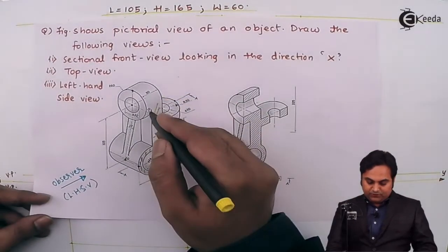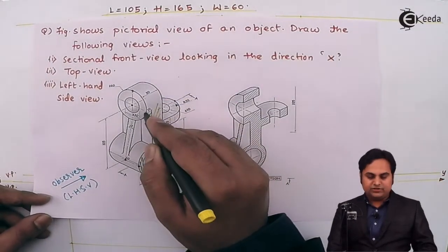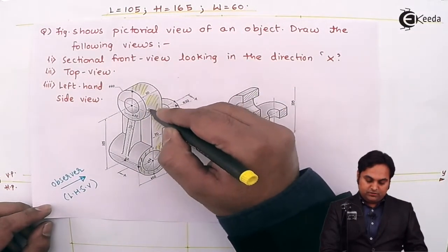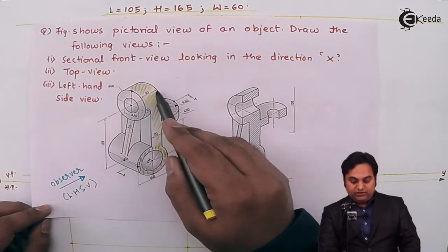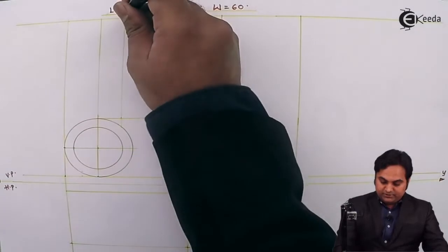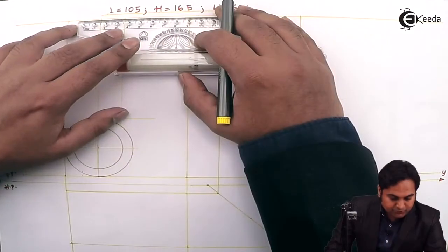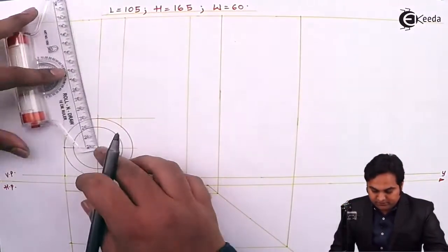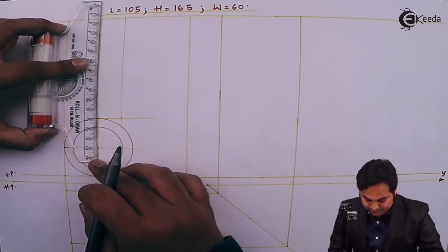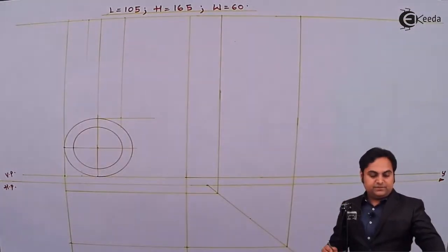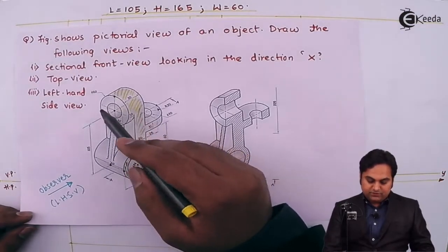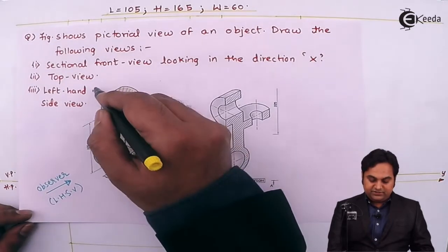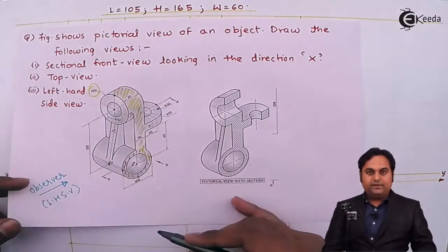After that, from this center, that is exactly at this location, another length is 10, and this cylindrical block is also seen from the front, having a total length of 30 mm. So from the top where this portion has ended, I am going to measure 30 mm from here. Already 20 we have, so measuring 10 mm and then plotting a light vertical line below. Next, this cylindrical portion has a total height equal to the diameter, which is 60 mm. So from the top I am going to measure 60 mm.